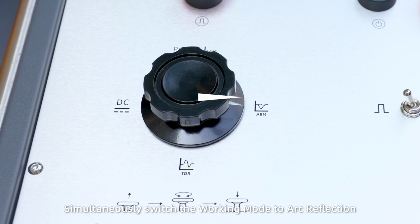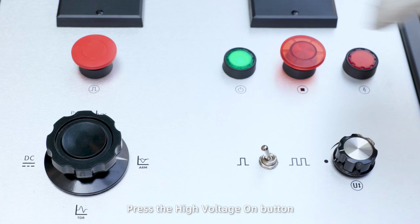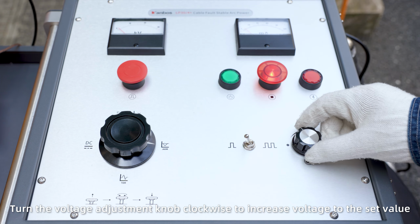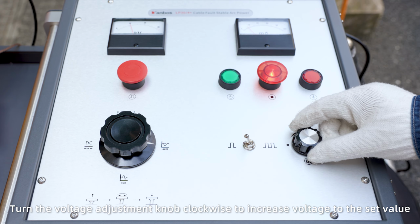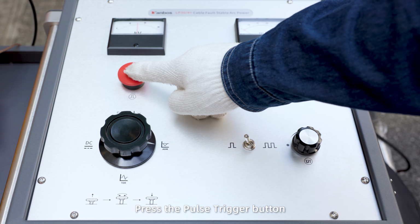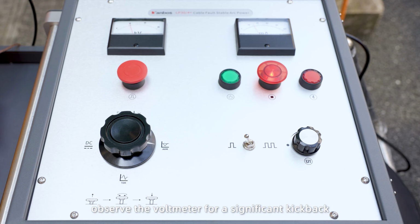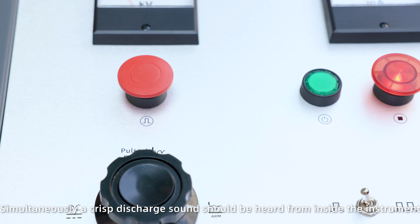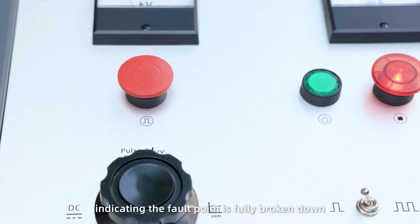Simultaneously, switch the working mode to arc reflection. Press the high voltage on button. Turn the voltage adjustment knob clockwise to increase voltage to the set value. Press the pulse trigger button. Observe the voltmeter for a significant kickback. Simultaneously, a crisp discharge sound should be heard from inside the instrument, indicating the fault point is fully broken down.